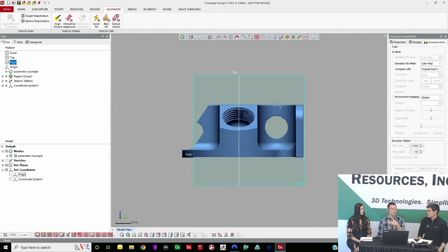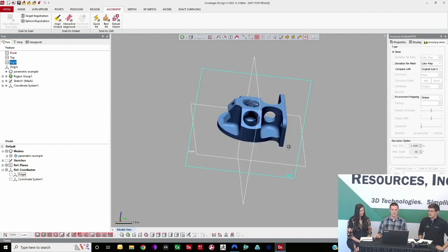The other reason would be the CAD model. Once I finish building it, whatever manufacturing process I send it to, after it's finished in Design X, that CAD model is not going to be floating out randomly in space, right? When you bring this into your CAM software to program a toolpath, you want this to be at the origin right away, so that you don't have to program a toolpath somewhere out in space, and you don't want your machinist to have to realign this. It's just going to be there for him to begin programming on right away. Cool. Great. Okay, so let's begin the modeling process.